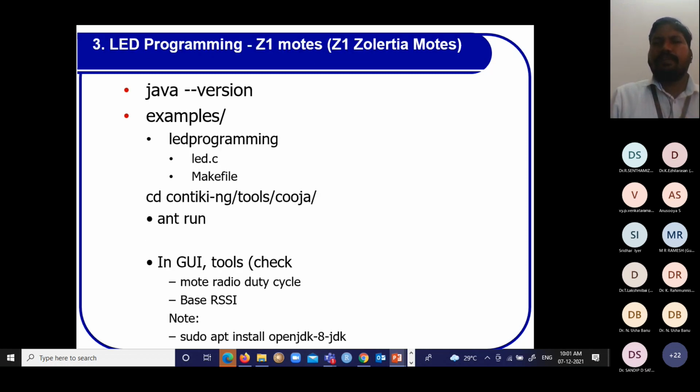We have a LED program. You can write a counter application with a timer; when the appropriate time is reached, the LED is going to glow. That event is emitted, and you can call the appropriate interrupt. So this program and Makefile you have to keep inside the LED folder. The other procedures are the same, but according to the application, you can test its functionality.